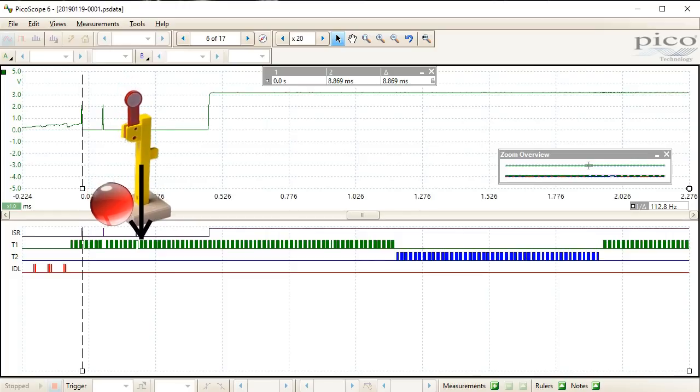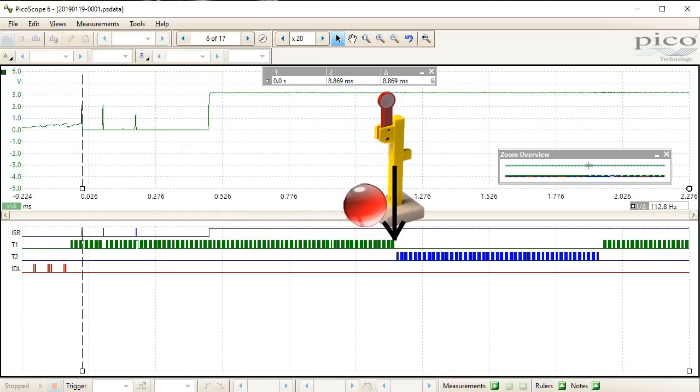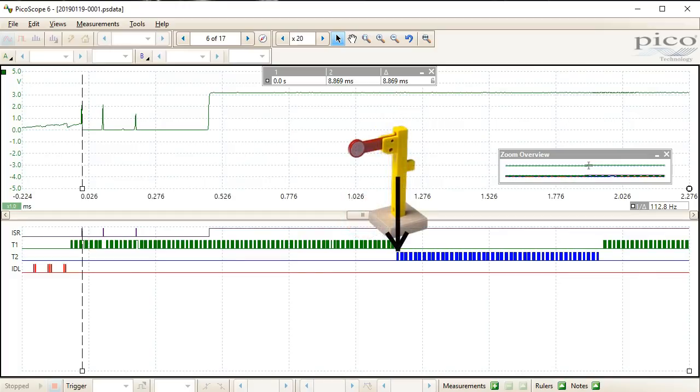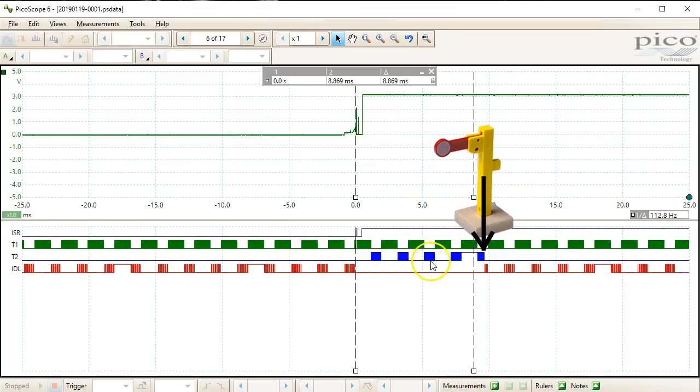The high priority Blinky1 thread kept running, but finally blocked on the delay operation. Only at this point the preemptive QXK kernel scheduled Blinky2, which unblocked and removed the token from the semaphore. Finally, Blinky2 looped back to the top of its while(1) loop and called the semaphore wait operation. This time the semaphore was empty and so Blinky2 blocked.